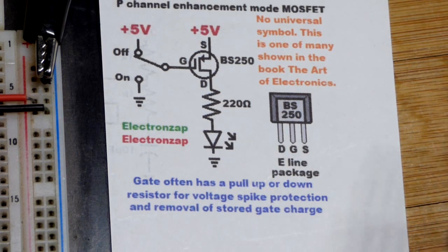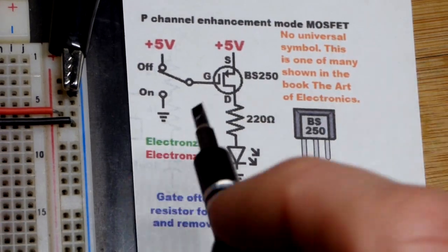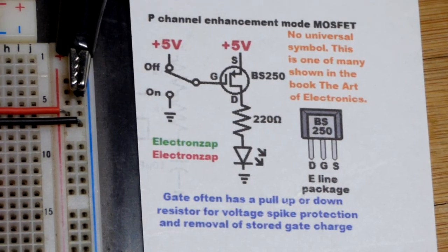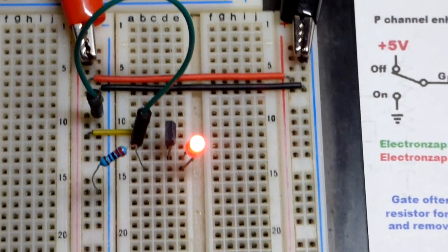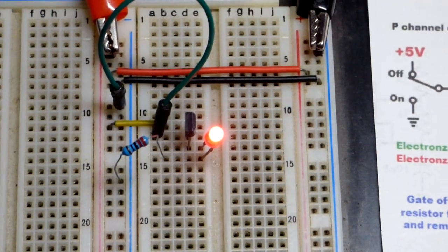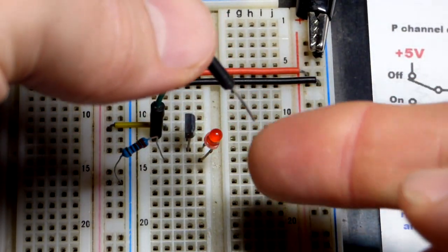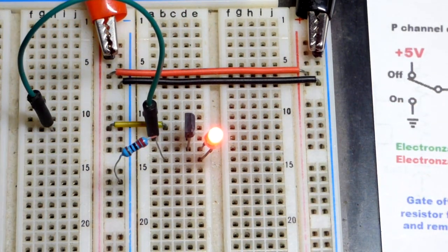And if you want to avoid that, you can use a pull up or pull down resistor. I don't put that on the schematic of all of the circuits that I do. You don't really need one if you have a digital output, because it's either high or low. But as we saw before, we have this kind of anywhere in between fully on and fully off right there.